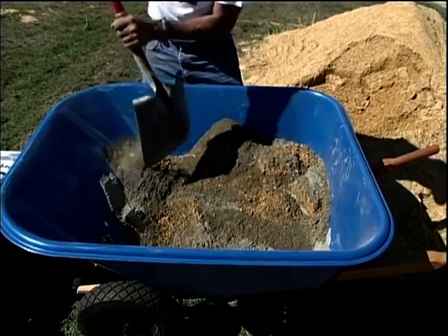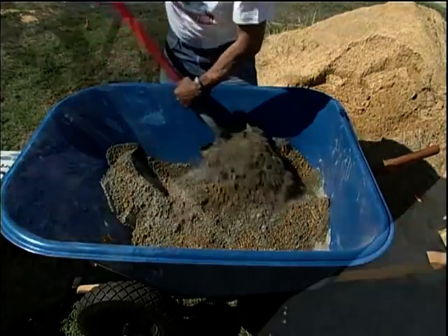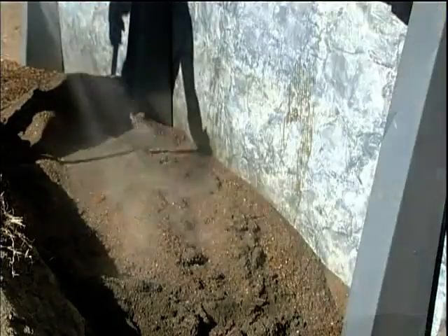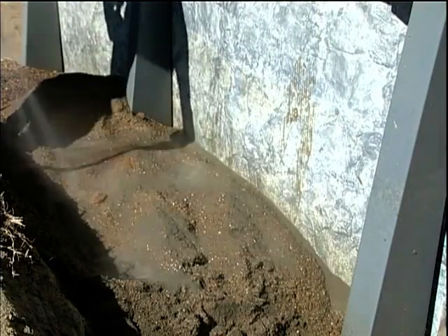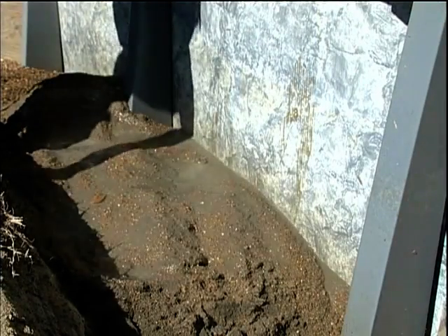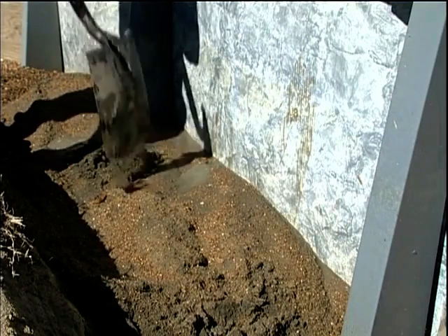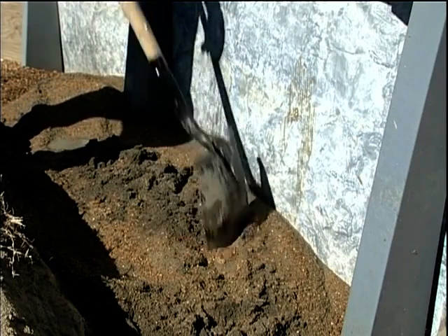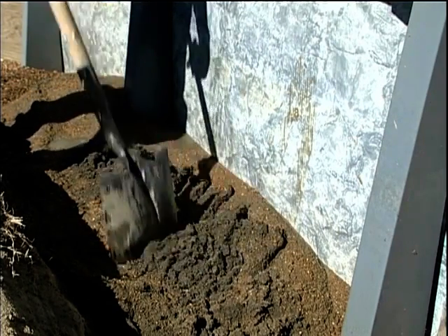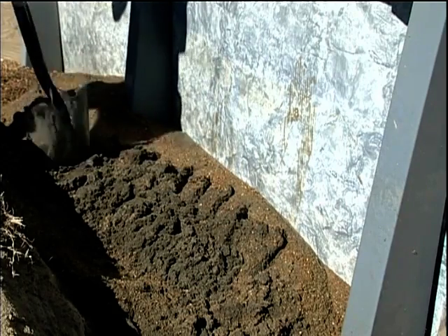The first way is to mix the sand and gravel dry. Then shovel this dry mixture into the area around the pool. Next, add water into the mix, allowing the water to penetrate deep into the mix. Wet the mixture until it reaches the proper slump consistency. Finally, tap down to compress the mixture and continue this process until you have reached the finished level.